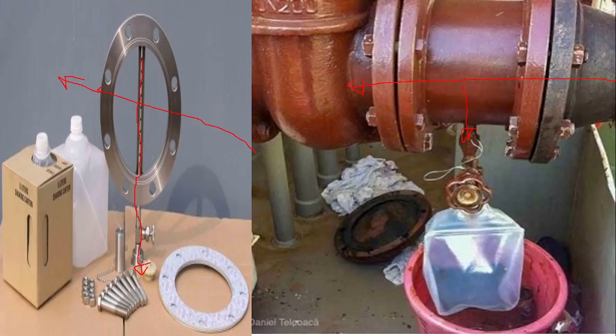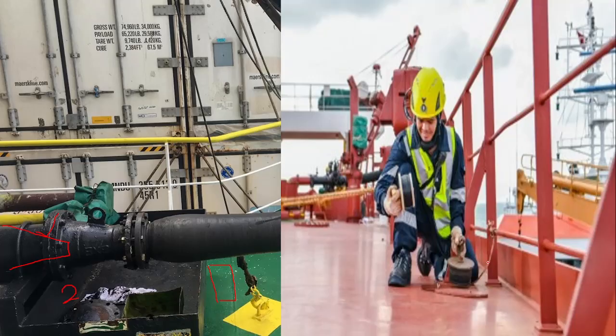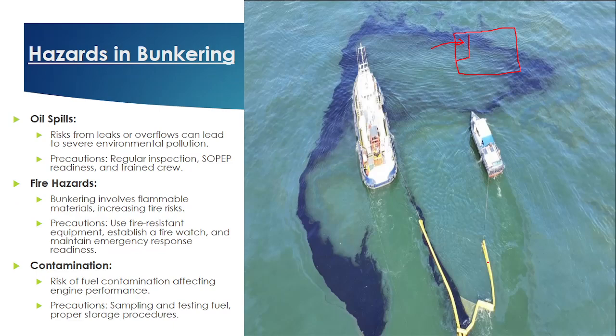This you will send to the lab, and the lab will report the amount of sludge content, the amount of sulfur content, or the amount of sediment, and you can give this to the company and they will fight against the bunker delivery barge. So the contamination can be fought by the company, but you have to collect the sample properly and send it to the lab.